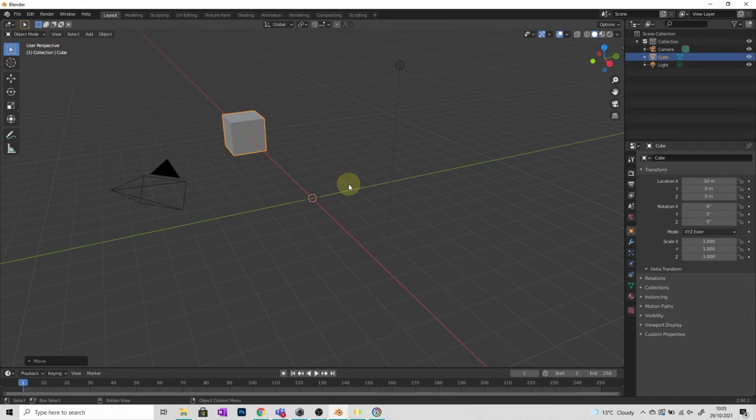You can tell if you're going in the negative direction by looking at the value in the top left and also looking at your gyro in the top right. You see we have an X, Y, and Z colored icon here, and we've got the same colored icons but without the letter on. That means they're in the negative. So the red icon here without the X in it is the negative X. The red icon with the X is positive. And that simply means you're adding a minus or just a normal number when you're moving your objects.